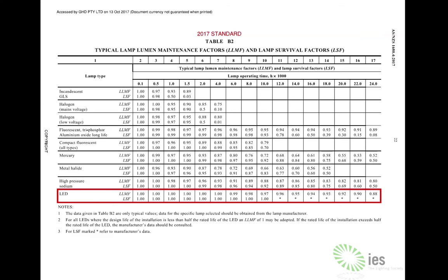Being a DC source, there's no point where you're switching at an uncomfortable angle on the sine wave, but that does happen at drivers, and you might switch at your zero crossing, you might be switching at the top of your peak. That can affect your inrush currents and start tripping circuit breakers. That's one I've heard a lot of recently about LEDs, where switching them on at the top of your sine wave, and as a result, you get your inrush current and your circuit breaker goes ping.